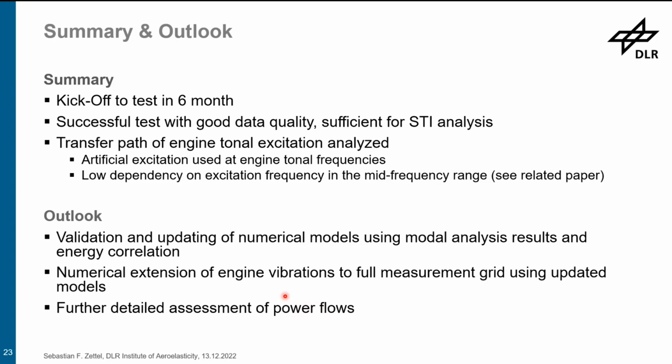We used the artificial excitation for that because we don't have the structural response for the full engine runs. And we identified a low dependency on the excitation frequency in the mid-frequency range because of the high structural damping of the aircraft. The outlook regarding this project is that we want to validate and update numerical models using the model analysis, and also do energy correlation to improve the model updating.